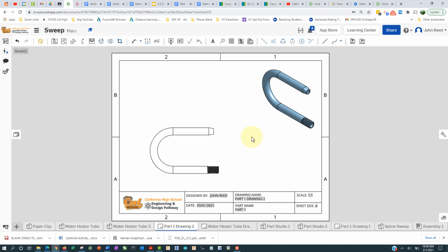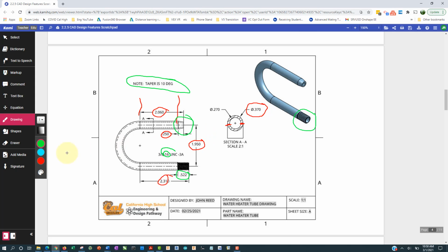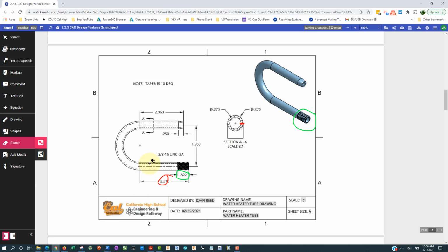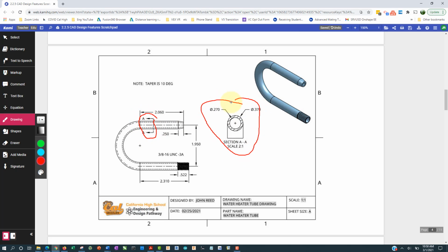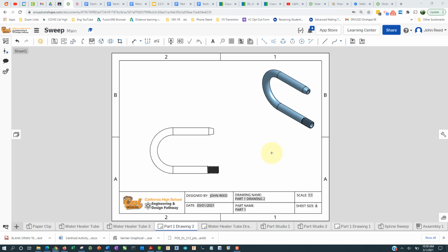Now, for that cross section here, what we want to do is make this section view right here. So we have that section view there. And remember, the way to read this is that where our eye is right here, looking right to left, looking in this direction, this is what we're going to see if we chopped all this away, and that's what we'd see right there.